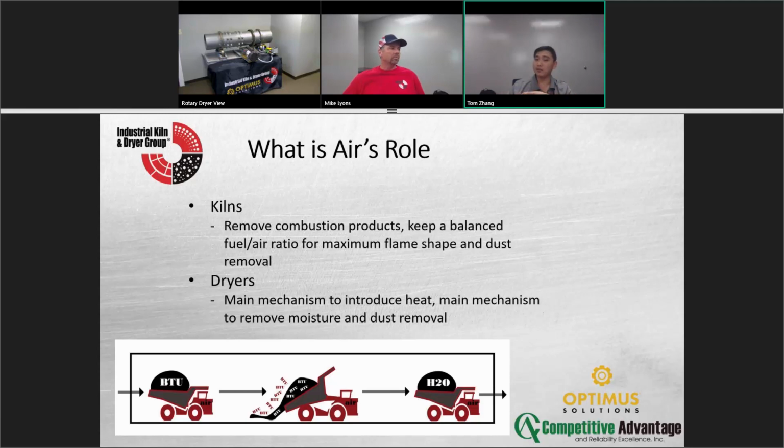On a dryer, on the other hand, it's almost a full-blown lot of air because that's the job, right? So if you see that example at the bottom, your BTUs go in, your BTUs exchange with the air. That's the truck itself. BTUs go get H2O. So that's on a dryer. That's the job of the air. Without air, if your ID fan's out, you can't do anything. So air is a very critical role.